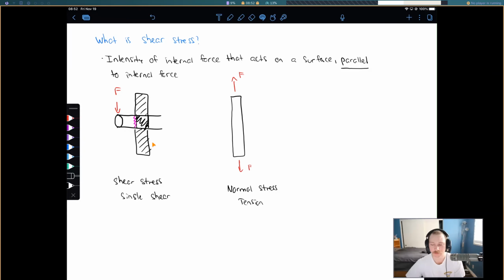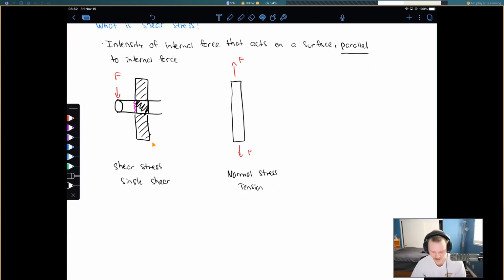Okay. So shear stress. So we'll go over that formula. So we're going to write this as tau. Okay, so tau, that's going to be the shear stress, and we're going to have this equal to V divided by A sub V. So I might put either V, I might put F, I might put P. It doesn't matter.